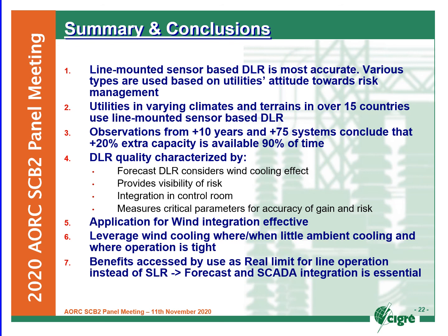Finally, the benefits of dynamic line rating are accessed by using them as the real-time limit, or the real limit, for line operation instead of the static line rating. And for this, forecast and SCADA integration is essential.